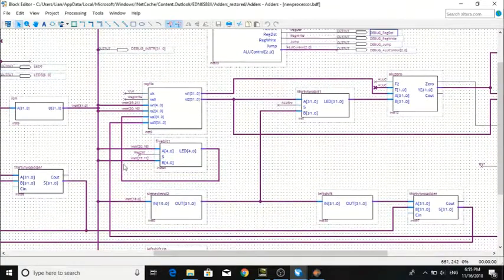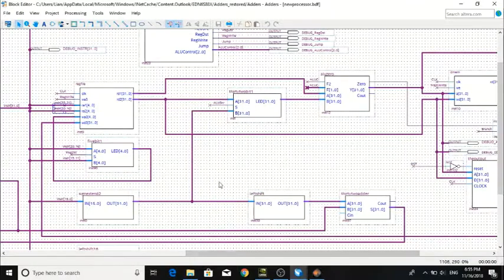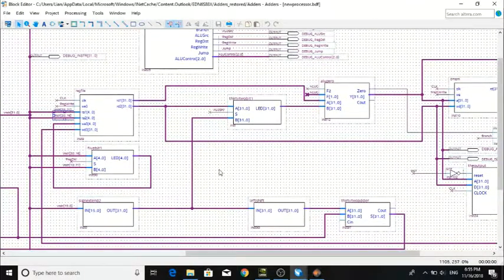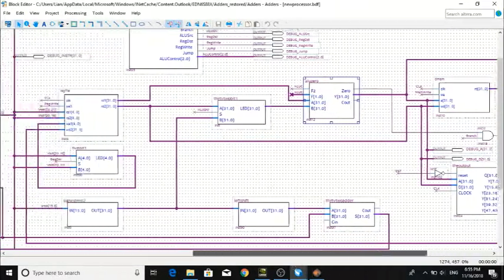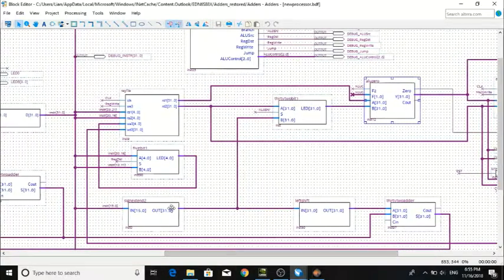The data in the 2 registers from bit 25 to 21 and 20 to 16 needs to be compared. Hence, they are used as the 2 inputs for the ALU. These inputs are used in the ALU and they are subtracted. If the results are 0, which means that they match, the program counter is set to program counter incremented by 4 plus the offset.